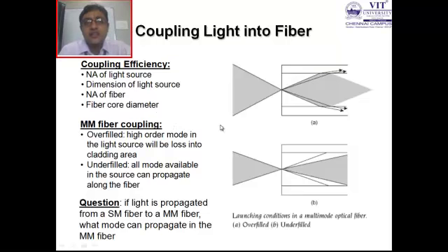Multi-mode fiber coupling has to be avoided. It's always sensible to use a single mode fiber, because when you have multi-mode fibers, you have optical power dissipated and distributed among many modes. And when I talk about single mode fiber, you have only one optical mode traveling through the fiber, with the maximum intensity concentrated in it. Now that is a sensible way. It's a sensible way to have an SM fiber, a single mode fiber, rather than an MM fiber.